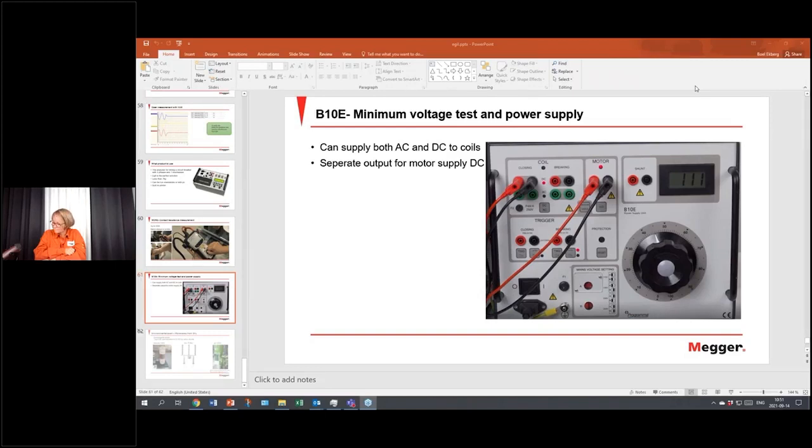He has also another question, which is how often should all of these tests be done, or what informs each test? When you should do the test, that's a difficult question. When you look at nuclear stations, for example, they test every year, but of course they are really, really important circuit breakers. So it's a matter of how important your breakers are. But I would say, at least, test every 5th year.